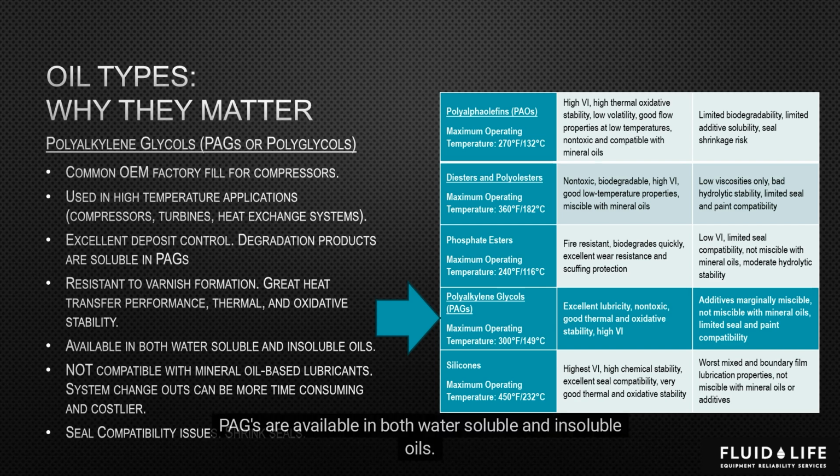PAGs are available in both water-soluble and insoluble oils, but they are not compatible with mineral oil-based lubricants. System change-outs can be more time-consuming and costlier because of this. One thing to watch out for with PAGs is seal compatibility, as they tend to shrink seals.